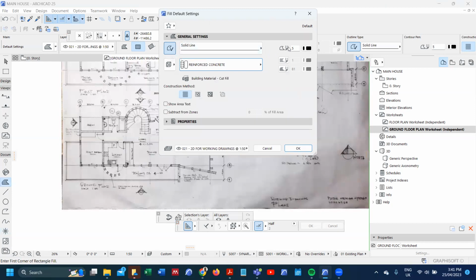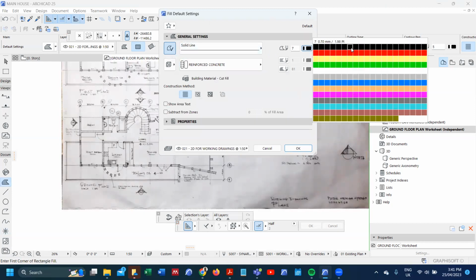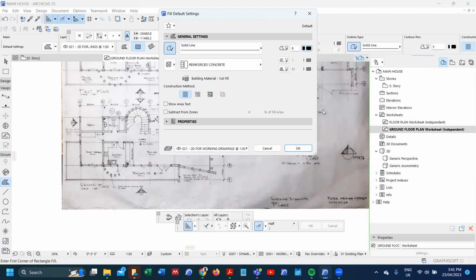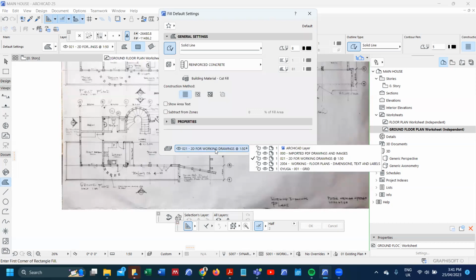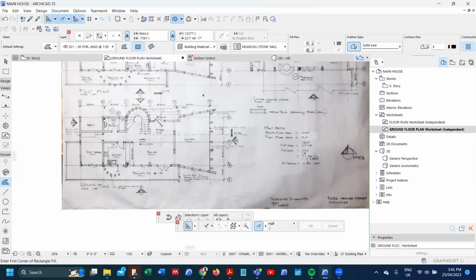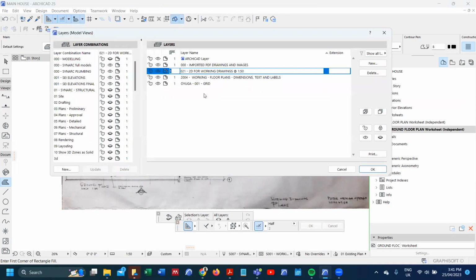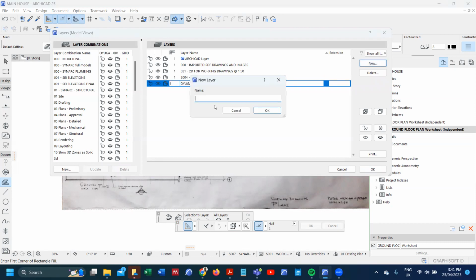And then in terms of the edge, just like usually in drafting, we'll use a pen that is thicker. And then I will change the layer, ensure that you use a proper layer so we can have a layer of building elements. I can view the specific columns.